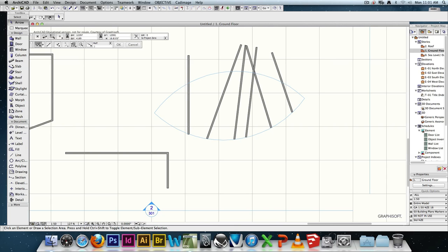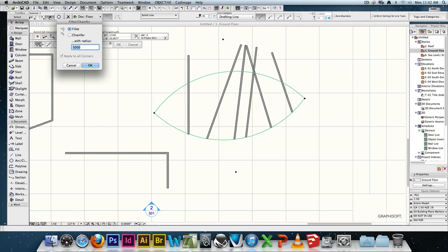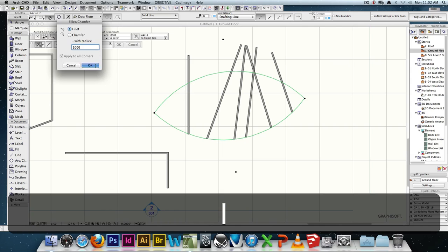All right. So we've trimmed, we've chopped, we've adjusted. We've also got that fillet tool in here. Remember the other day I grabbed the corner of a slab, I think it was, or a mesh, and I rounded off the corner. I don't know if this will work with two curves, but let's give it a crack. You go like that, 5,000 radius. No, it's a bit extreme. Let's say 1,000.